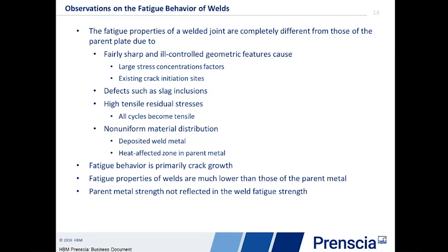Finally, the last couple items. One, we'll see, and I think primarily because of the discontinuity in the geometry and the initiation sites, fatigue behavior of welds is primarily crack growth. If we look at the slopes of the SN curves and look at the behavior, they basically follow crack growth behavior.